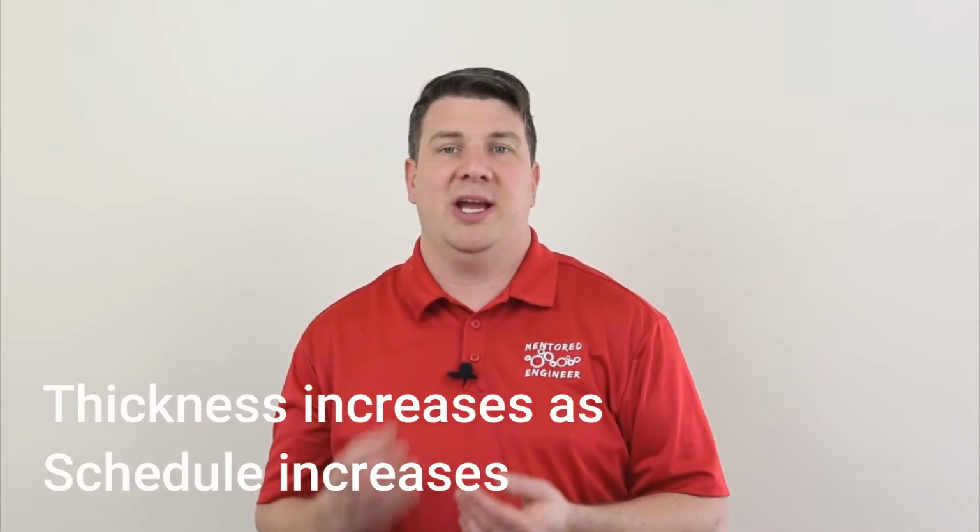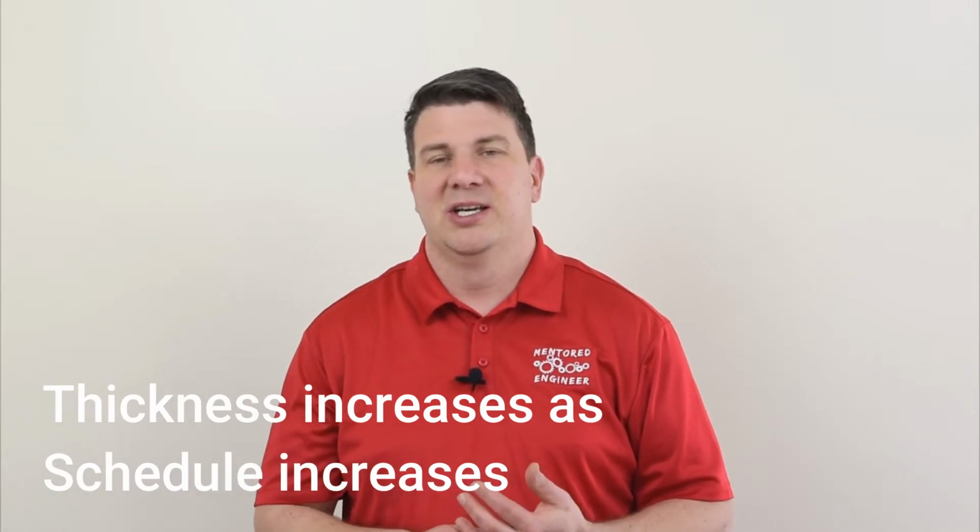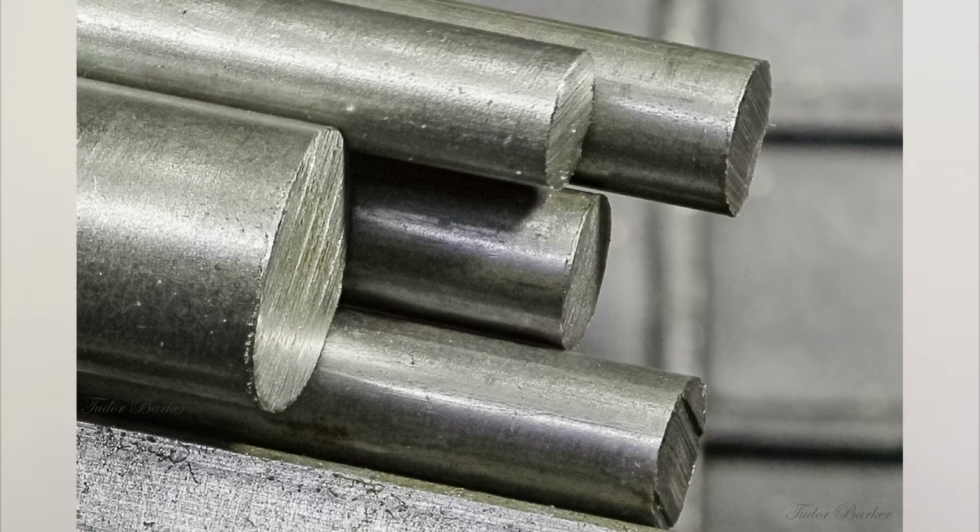One thing I do know is that in the smaller sizes, if you have a 3/4 inch pipe, the ID is about 3/4 inches when you have schedule 40. This brings me to my next point, that the thickness of pipe is measured in schedules. You have, generally speaking, 10, 20, 40, 80, 120, and 160. With that said, the OD of pipe is well toleranced, but the ID is allowed to free float as much as it needs. Let's move on to bar, because bar is where we're going to spend a lot of time.